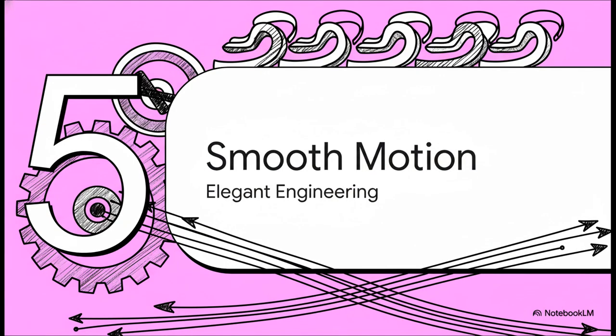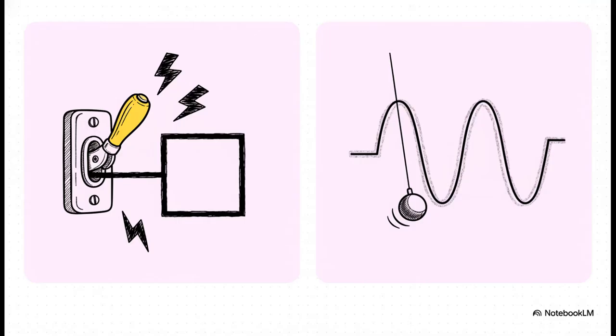But it's not just about the pattern. For weaving at high speeds and getting high quality, the way the threads move is just as important as where they move. And this is where the engineering gets truly elegant. So, when you design a cam's curve, there are 2 main approaches. The first is linear motion. It's the simplest. It just moves the threads at a constant speed. Think of it like flipping a light switch. Bam, on. Bam, off. It's abrupt.